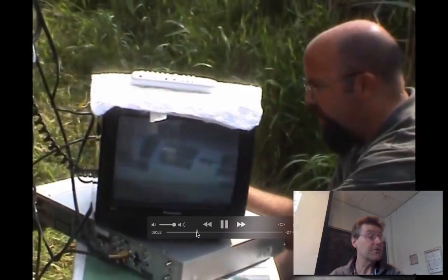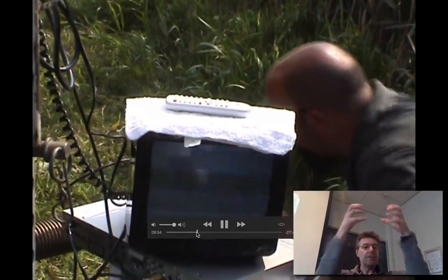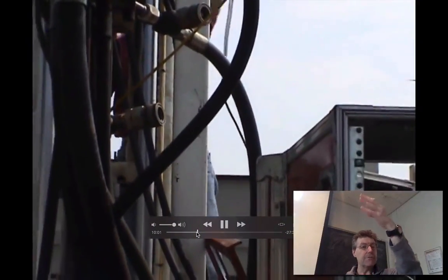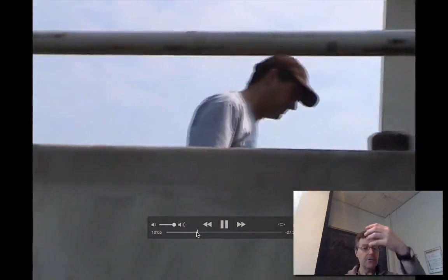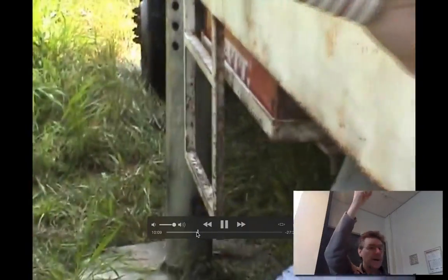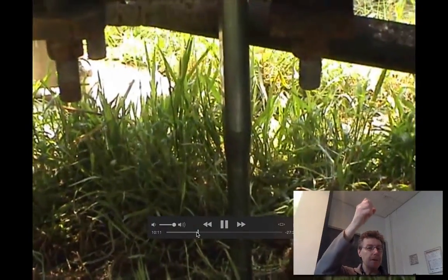Well, yeah, it's quite straightforward. So you grab this thing at the top, you push it into the ground with this stage that goes down. As it's going down, you're screwing another 3-foot length onto it, so that by the time it gets to the very bottom, you stop. Then it takes a couple of seconds to pull this thing back up to the top, grab onto the top again, and then repeat. And again, as it's coming down, you put on another 3 foot of rod.